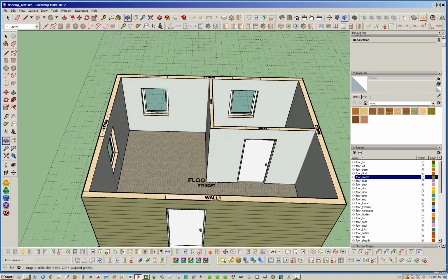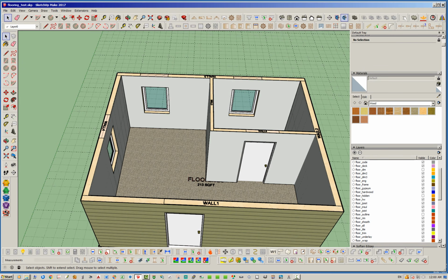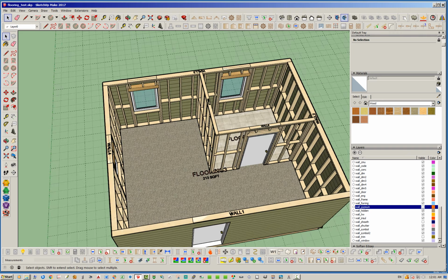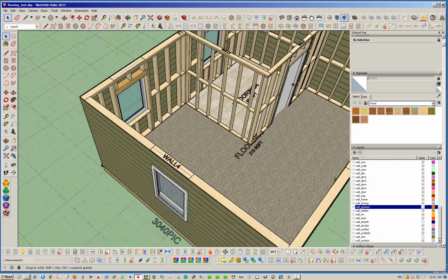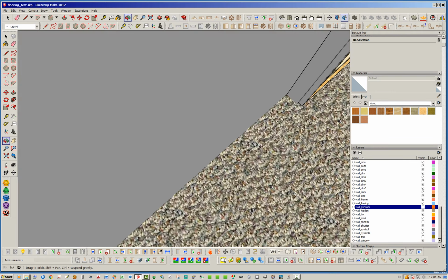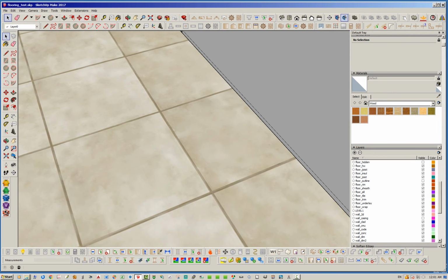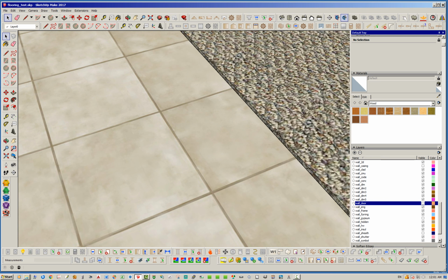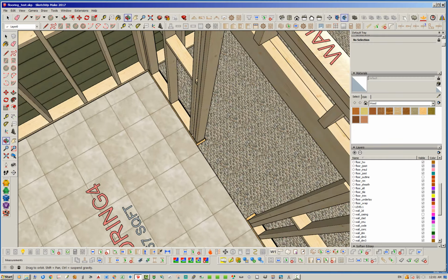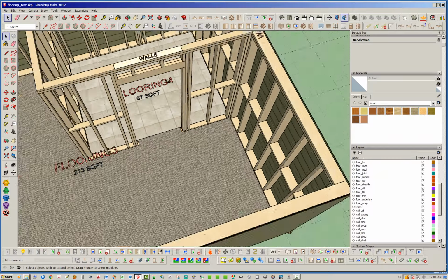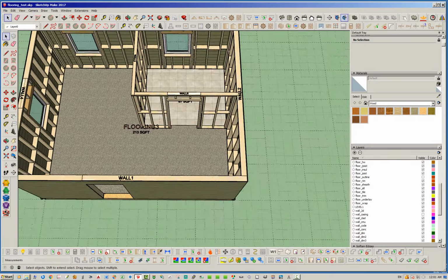All right, yeah, I think that's pretty good. Let's turn off our gypsum right now and just double check, make sure everything looks like it's in the right spot. So if we get close here, we can see we should have about a 1/2 inch gap all the way around. Yep, and we do. And as you can see here at the threshold of this door, let's turn off our door hardware actually, just to take a quick peek at that. Where's my wall door? Right here, and then there's the door hardware. Well, we can turn off. Yeah, all right. So you can see we've got the carpet coming right up against, butting up against there like it should, and you know we've made allowance for the door for casing and framing. Yeah, so everything looks good as it should, and that's basically it.